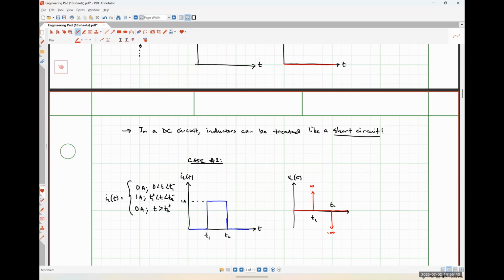Thank you for that, Joseph. So, an infinite voltage means that there has been an infinite transfer of energy, right? Because voltage is the amount of work done or the energy required to move charge around our circuit. So, if the current in our inductor were to change instantaneously, it would cause an infinitely large voltage to appear. Well, that can't happen, right? So essentially, if the current flowing through an inductor changes abruptly, we accidentally break the laws of physics.